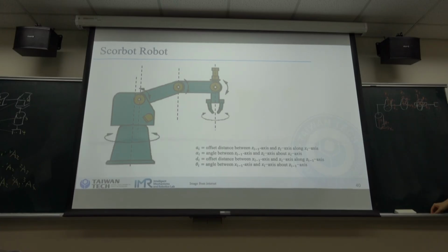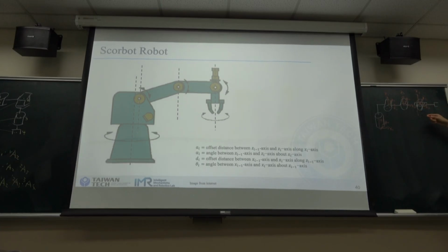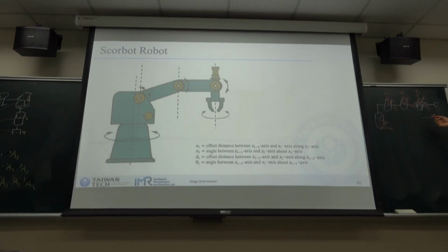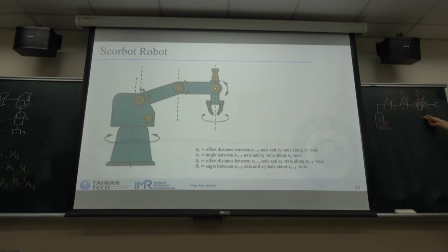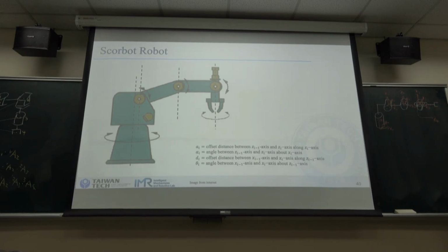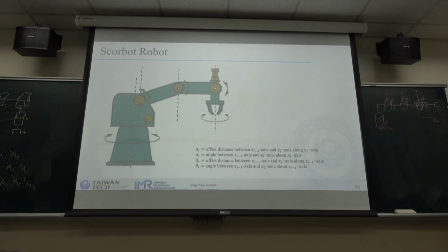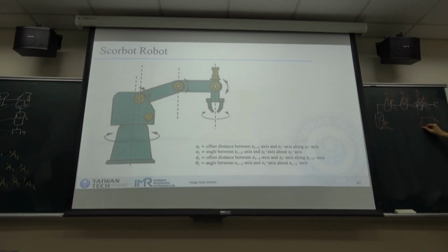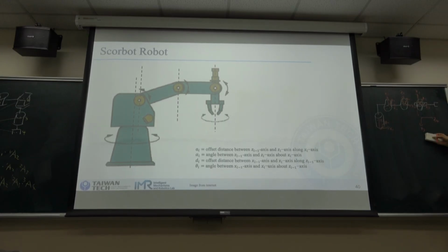The fourth one is different. We know that the Z-axis should be pointing forward. And then the X needs to be perpendicular to Z3 and Z4. So Z3 is pointing upwards, and Z4 is pointing forwards. So the only direction left for X is pointing out of the page. Sorry, it's X4.